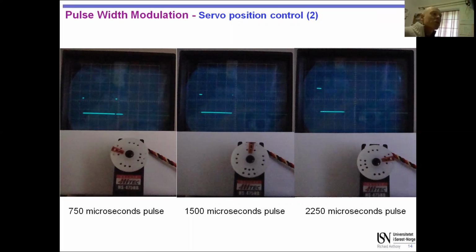So you might want to say, well, let's preset 8 increments, and we'll have 8 different pulse widths that correspond to those 8 positions. We can make a program where the camera points over there, then there, then there, and then goes back to there. And that's automatic. And that works better than just sweeping like this, because if you move a camera like this, sometimes the image is just blurred and it's not really good from a security point of view at all. So maybe this is better.